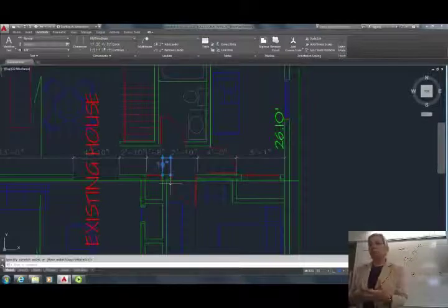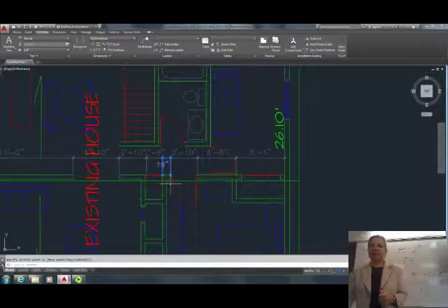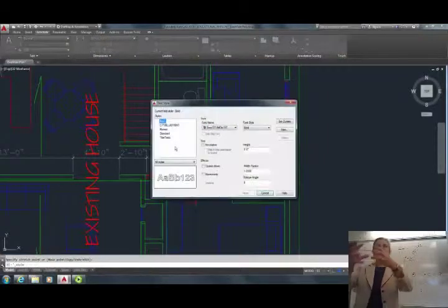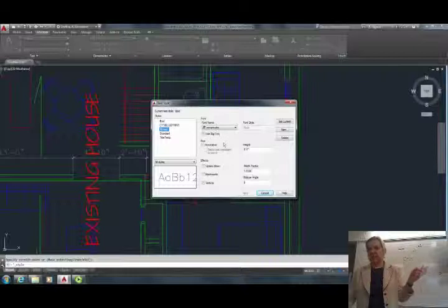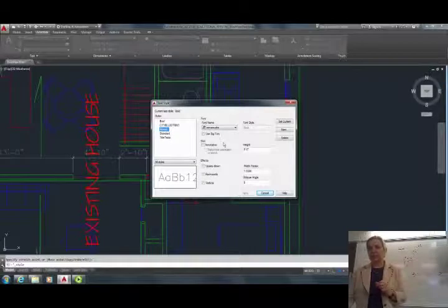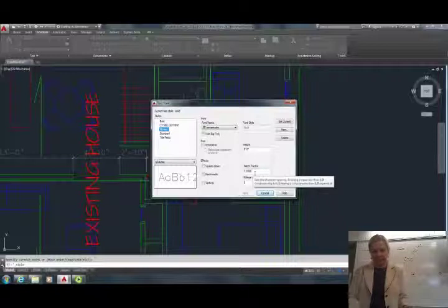I think that for this Roman text, I might actually go back to the text setting. If you want to try it, I haven't done it yet, I haven't tested it, but under your Roman, let's try it, because I think it comes out quite spaced out. Let's try something. You see this width factor under Roman? How about if I make the width factor 0.75?